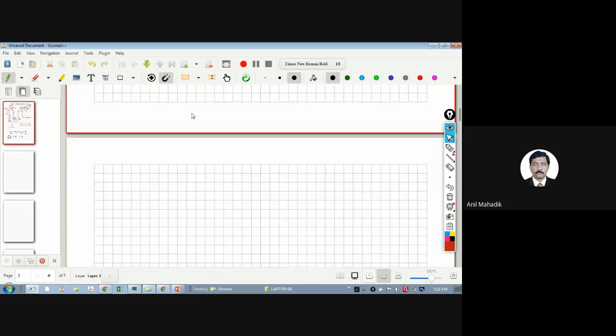Now I will ask you one fundamental question. Let's say you have an I section like this. For simplicity, I am just taking this as a rectangular part. Generally, there is a curvature. This is your I section. And let's say I'm putting one more plate over here, an additional plate. Generally, we call it a plate girder. Now tell me, if I calculate the neutral axis for this, this is your center of the I section actually. Will your neutral axis be below this line or above this line?